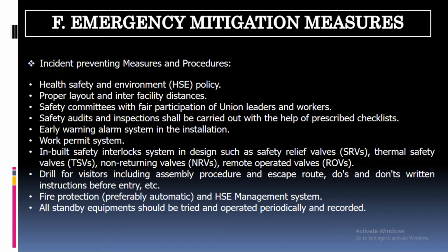And also we have to ensure that there are inbuilt safety interlock systems in design such as SRVs, safety relief valves, then TSVs, thermal safety valves, then NRVs, non-return valves, and ROVs, remote operated valves. Then there should be drills conducted for visitors including assembly procedures and escape routes, then do's and don'ts, written instructions before entry, etc. Then also the presence of fire protection and HSE management system should be there. All standby equipment should be tried and operated periodically and recorded.